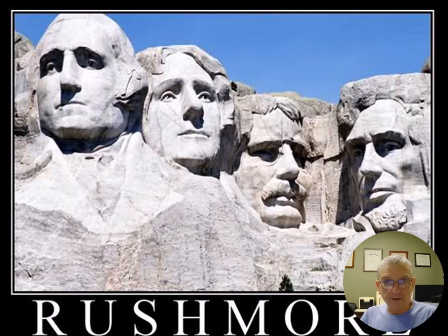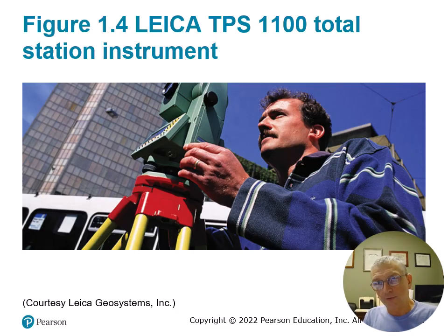Section 1.4 explains to the reader that there's a difference between plane surveying and geodetic surveying. Now, we don't mean plane as in plain old, we mean plane as in the geometric term plane, P-L-A-N-E. Most surveys that we'll work on in our careers are of a small enough area that we can treat them as planes, as if the world is flat at that point.